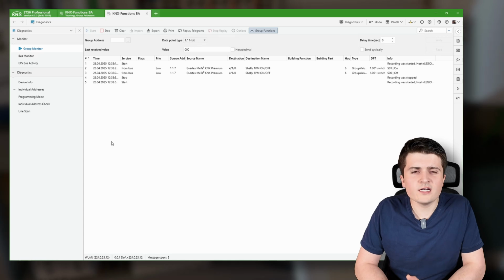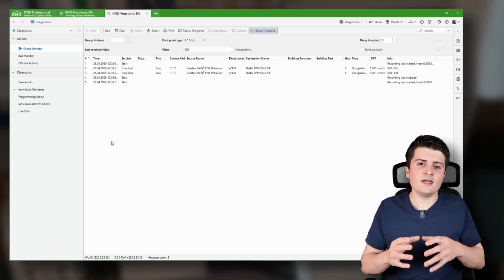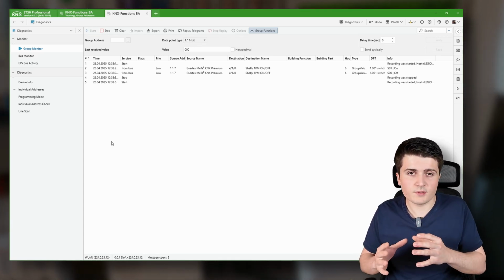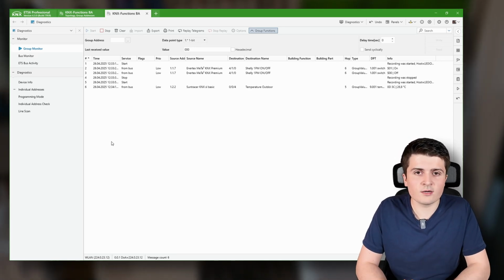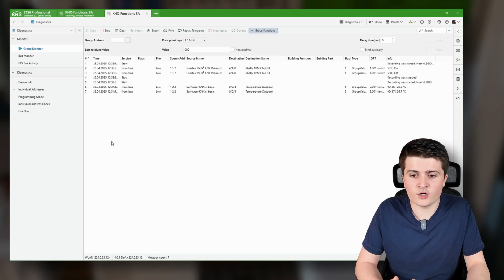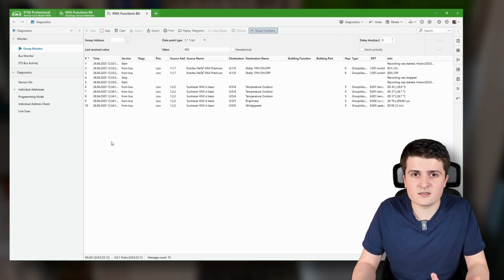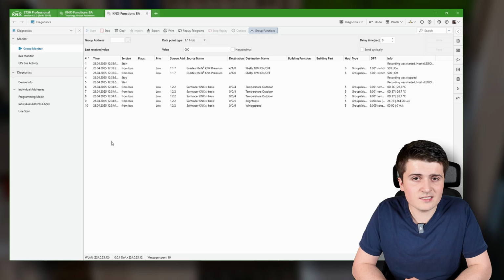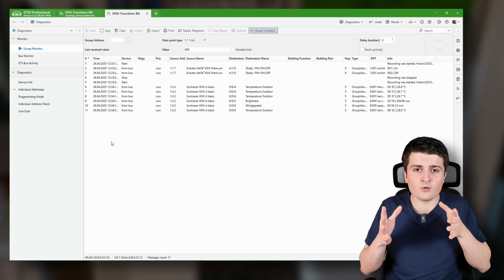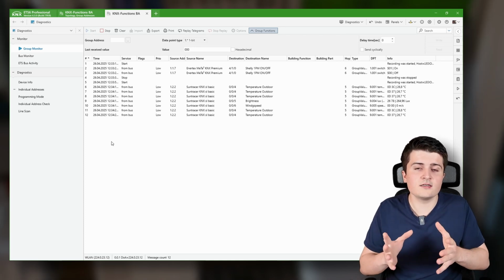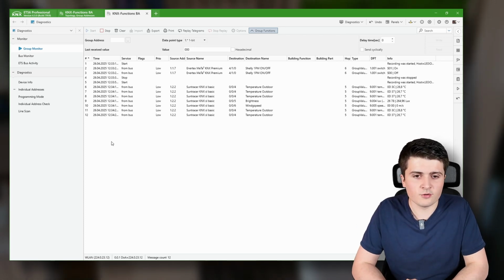And that's the real issue here, because in between the KNX IP side and the KNX twisted pair side sits a KNX IP router, which filters those telegrams that don't need to be converted. And as the ETS doesn't know anything about the Shelly device, that's the problem here, because then the ETS won't tell the IP router to let the telegram for the Shelly through.